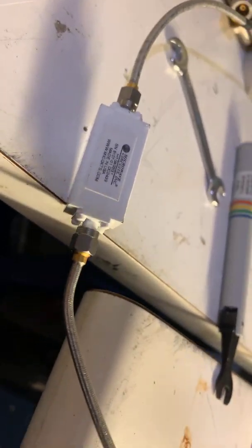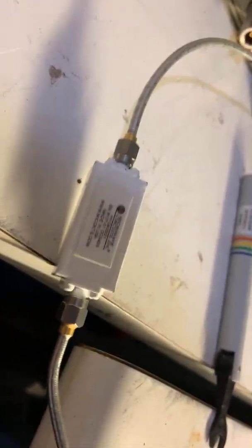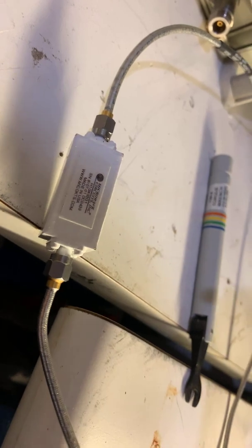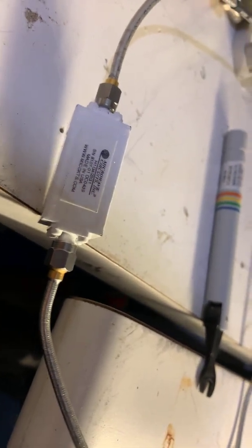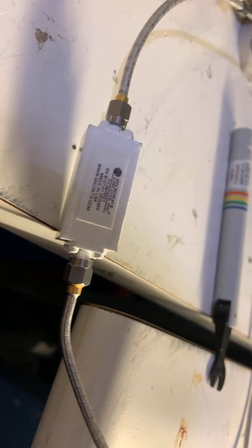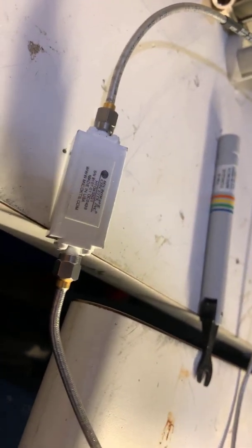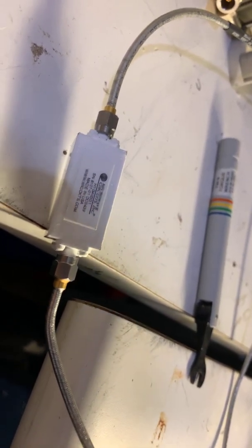So what the calibration basically does is it moves the reference plane to the reference plane of your cal standard. So in this case, the reference plane would be a little bit off because I used this adapter. So basically, the reference plane wouldn't be right here, it would be at the end of this adapter. Normally you should use a cal standard that has the same sex as your device under test, but unfortunately I only have a male calibration standard, so I kind of have to work around it. Normally there are ways around it, but right now this is just for demonstration purposes anyway. So this is how our response looks right now.